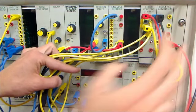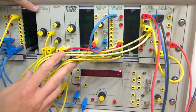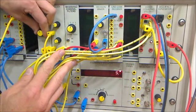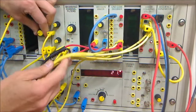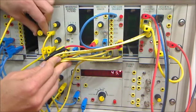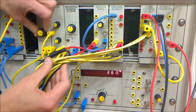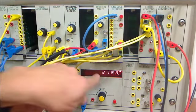So now that it's all lined up, our bit error rate instrumentation system is ready to count errors created by the noise in the channel. Okay, here's the noise generator. We've adjusted our levels at the adder. As I start to increase the noise incrementally from a very minimal level, you'll start to see small amounts of errors accumulating bit by bit. And now, as we get up to 14 dB, errors are starting to accumulate. The more noise in the system, the more errors accumulate, until we dial up till we reach a maximum level of noise.